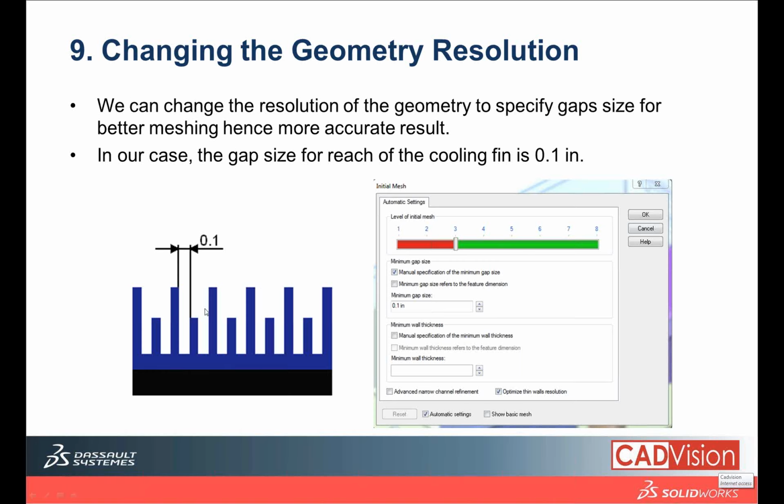Next, remember earlier we assigned the default resolution. Of course we can always tune it to the fineness for more accurate results. But tuning it to fineness simply means that it will mesh everything with the fineness settings, and results in very long computation time. You will get an accurate result, but it might take very long to finish your study.